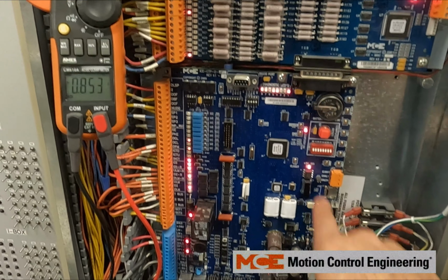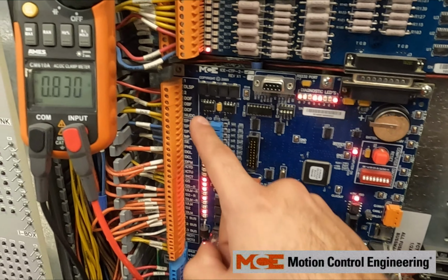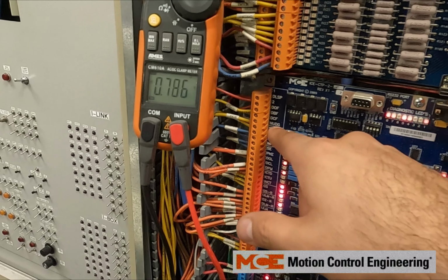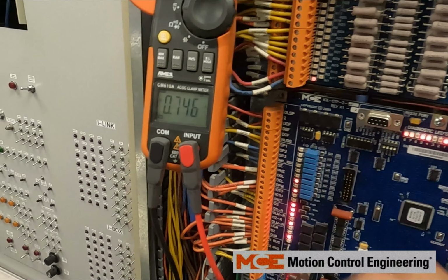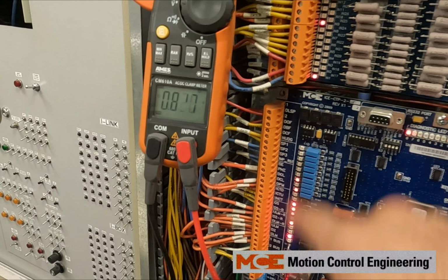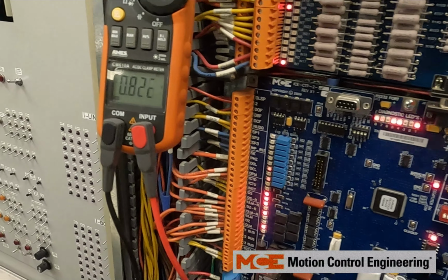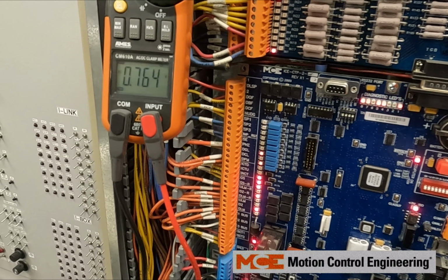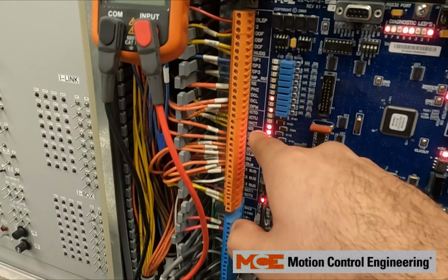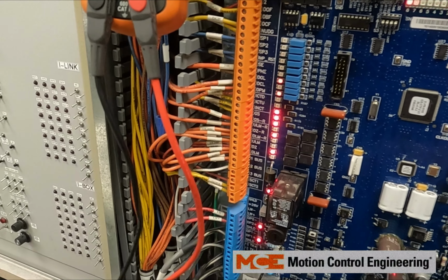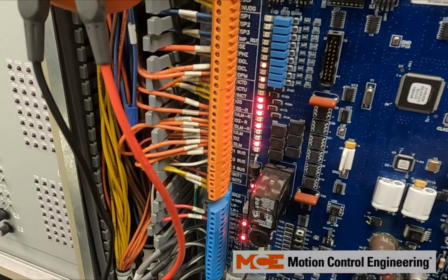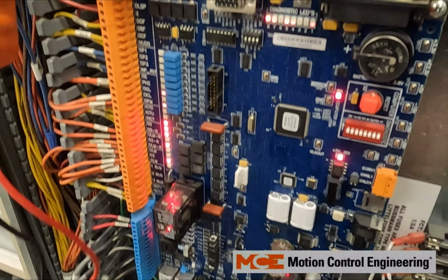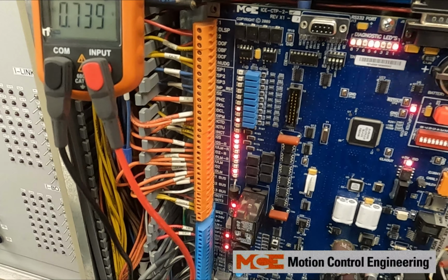Here would be our car top board. As you can tell right here on the left side, we'll have our door open function, door boost function, door close function, nudging. So that's all our outputs from the car top board. Our inputs from the door operator are right here. Right below it, you have door position monitor, door close limit, door open limit, photo eye, safety edge.